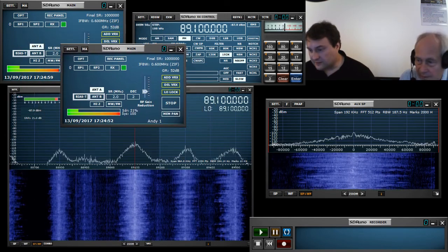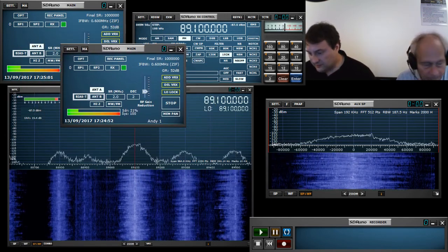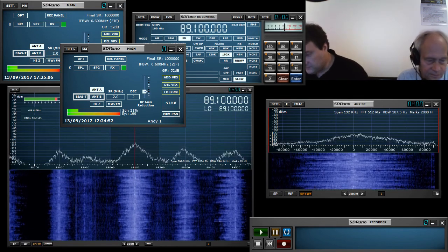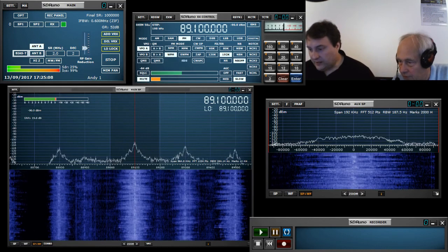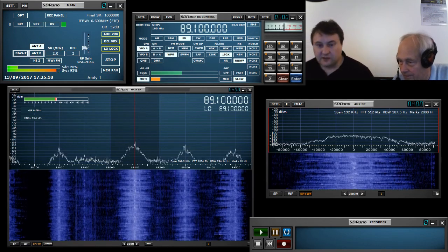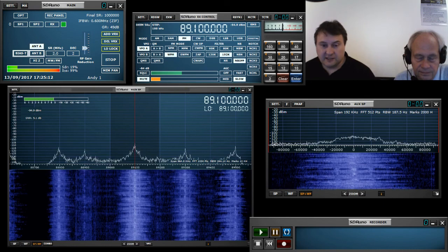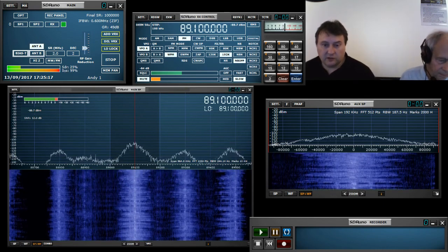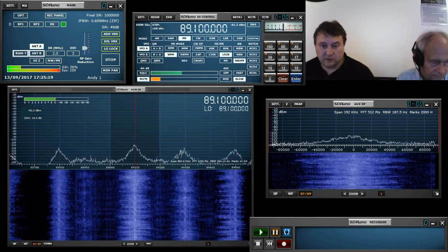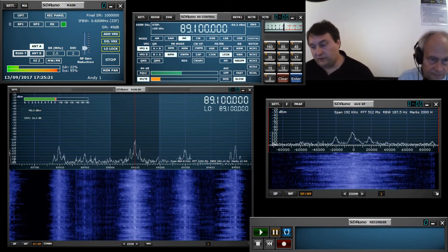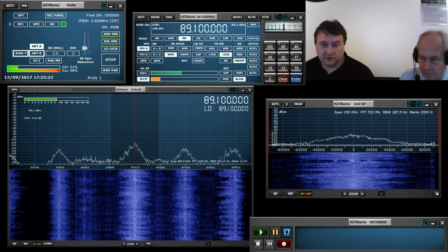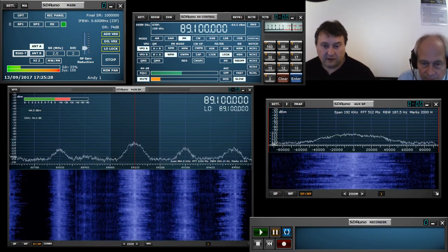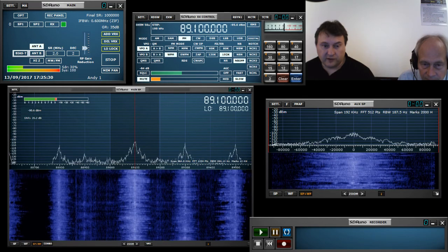That's interesting. For some reason, I'm not able to capture this because it's a sub window. But there's a settings panel on the main window, which will allow you to turn the IF AGC on and off. So at the moment it's on. If I switch it off, I've got a 40 dB window of gain control that I can apply.